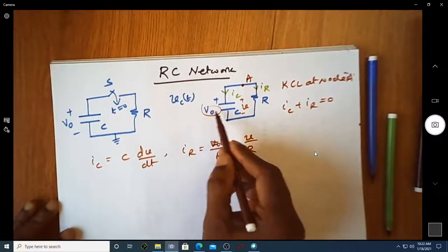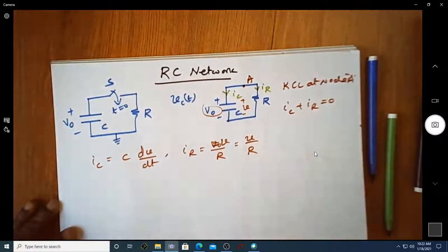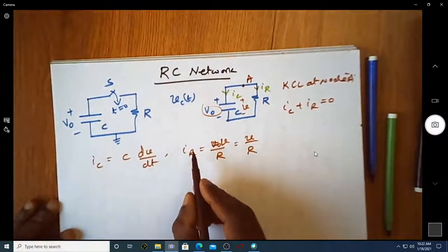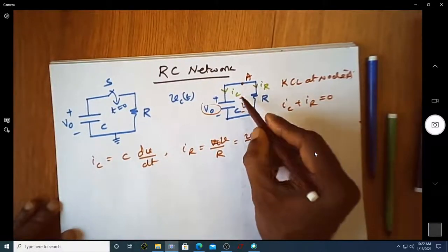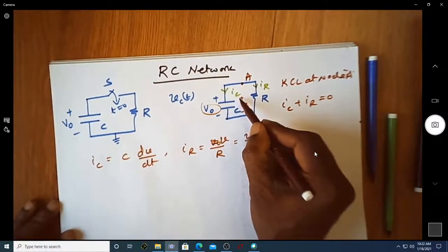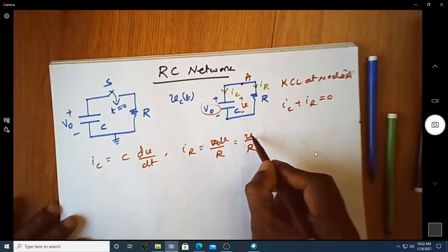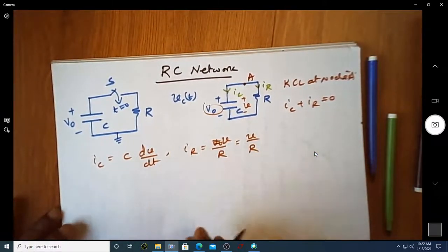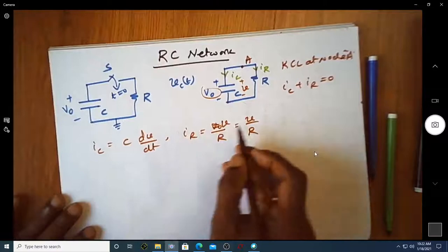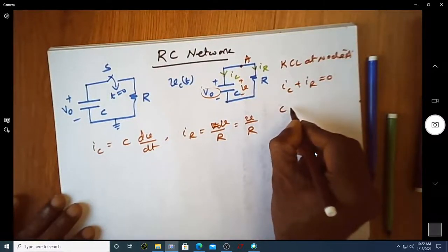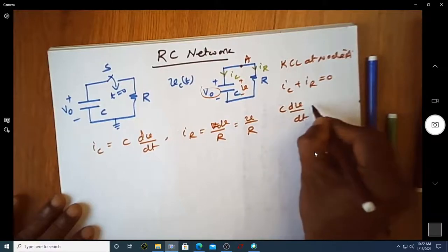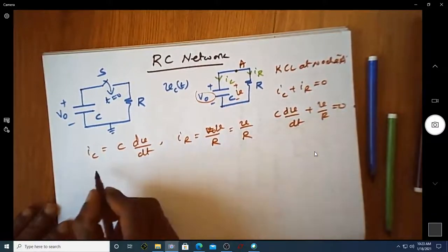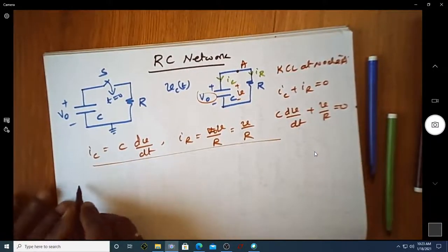Of course, V0 is the voltage across the capacitor when it is open, that is the initial voltage. So let us consider the current flowing through this is due to the voltage that is across this capacitor at any point of time. So let us take V as the voltage, and V by R happens to be the current flowing through that resistor R. So let us try to substitute that. Now this is equal to C into dV by dt plus V by R is equal to 0. So let us just try to solve that particular expression.